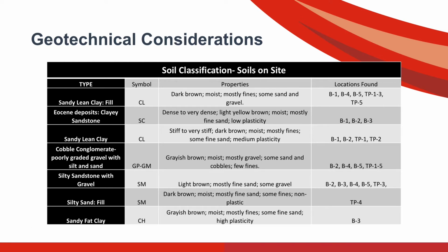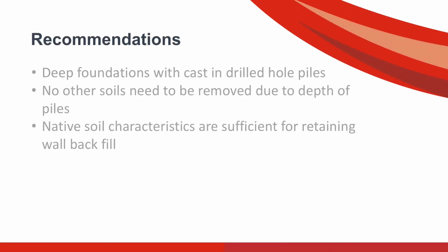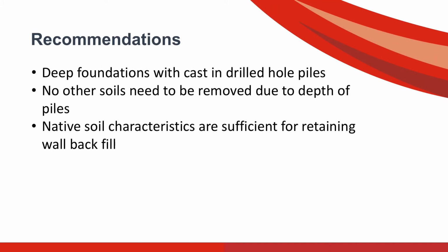These dense soils have the bearing capacity for end-bearing piles, as well as providing skin friction for the shafts. Due to the fact that these layers started at 15 feet below the surface or lower, a cast-in-place drilled hole pile foundation system was recommended. With these deep piles throughout the entire foundation, no soil needed to be removed, and the native soil was sufficient for the T-wall retaining wall system proposed by the structural engineers.